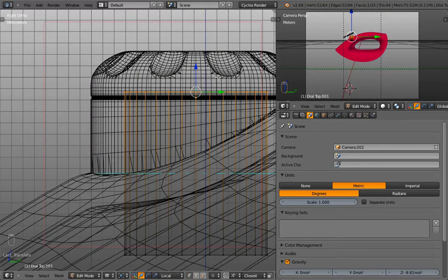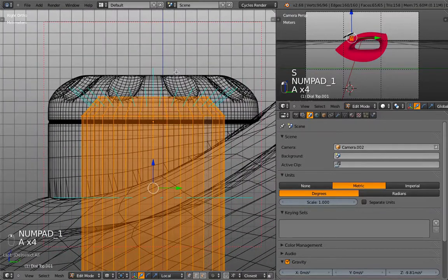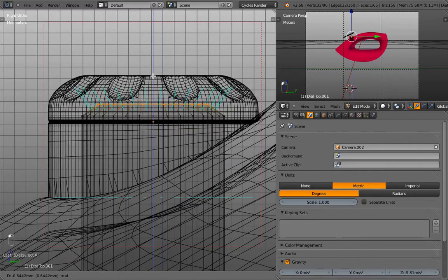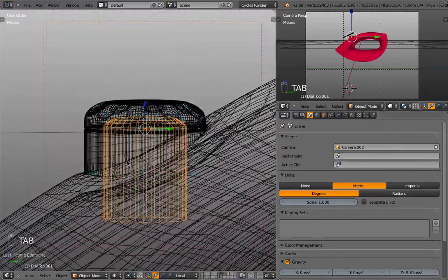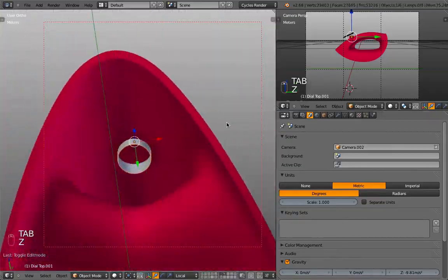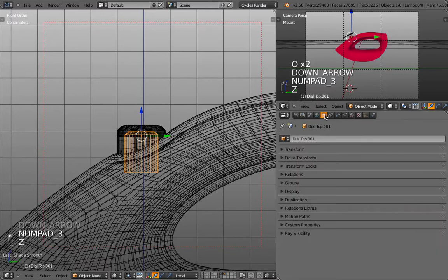And this roundness, for example, well, if I want to, I could extrude this face and then scale it a little bit. So you see kind of like the shape I have, but it's not really important to even match this roundness. So I will just leave it here. The material thickness here will be a little bit uneven, but again, for a quick rapid prototype for print, that's really more than sufficient. So I'm going to shade this one smooth, and maybe let's call this one top dial core out.